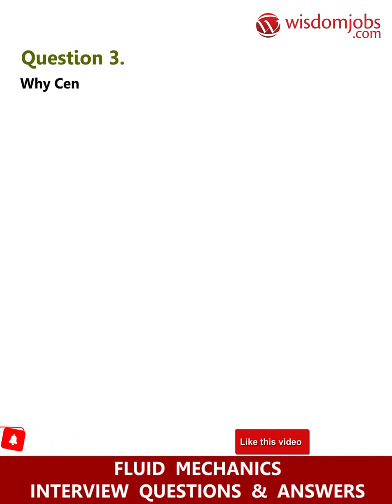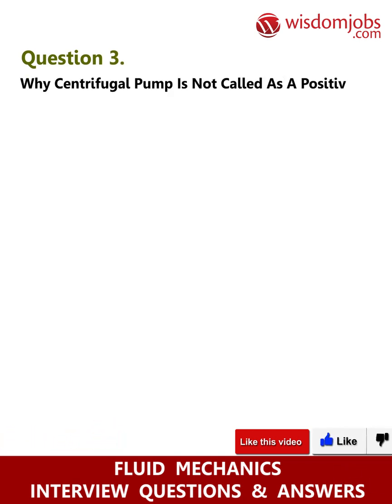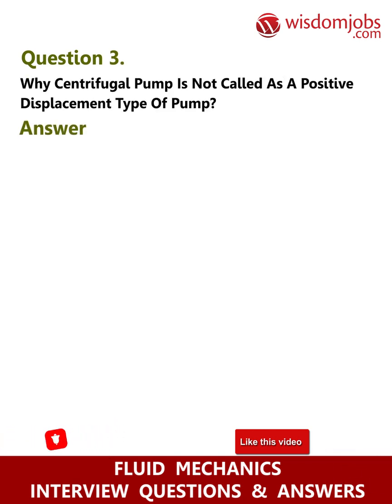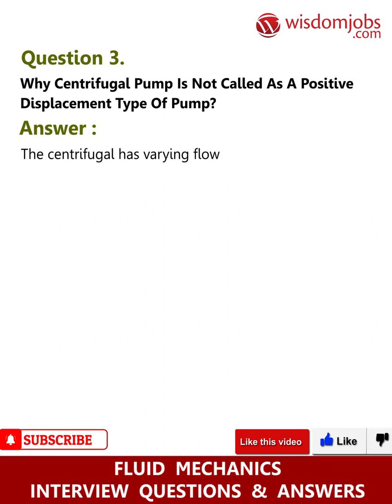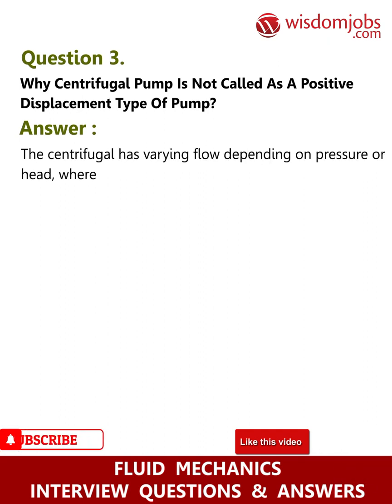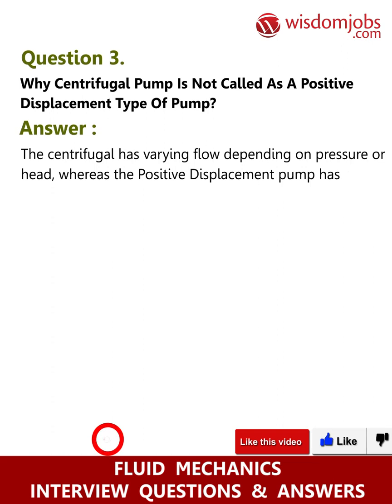Question 3. Why is a centrifugal pump not called a positive displacement type of pump? Answer. The centrifugal pump has varying flow depending on pressure or head, whereas the positive displacement pump has more or less constant flow regardless of pressure.